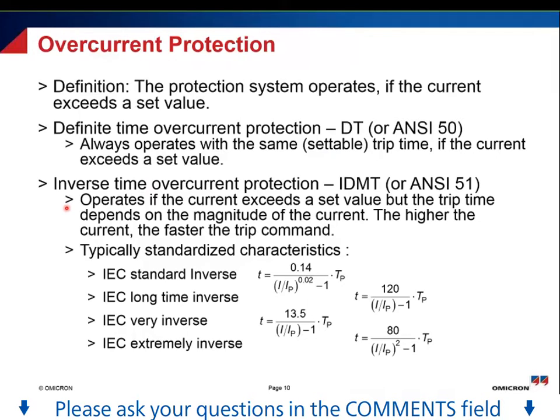Well, there is a huge amount of different inverse characteristics that can be used, but typically they are standardized. So in this case, you can see we have, for example, standardized by the IEC, different characteristics, the standard inverse characteristic, the long time inverse characteristic, the very inverse, and the extremely inverse. I also show here the formulas how to calculate the trip time based on the standard.